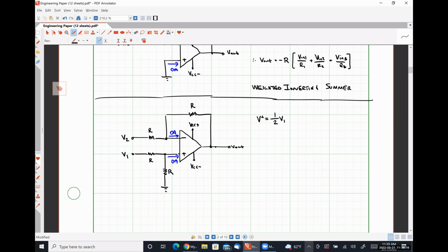So this is a simple voltage divider network. And we can treat it that way because we know that no current is able to branch off and flow into the input. So this input voltage V1 just sees 2 resistors R in series, and we're looking for the voltage drop measured across this resistor. Yes, sir. We can call it KCL, we can call it KVL, or we can call it voltage division, all kind of the same thing.